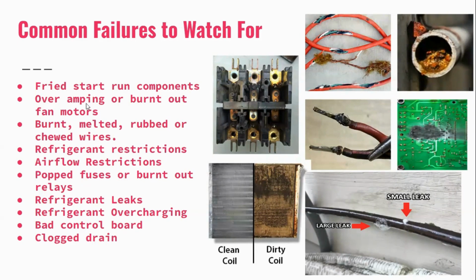And the reason I say always make sure you have an amp clamp on your meter is because we always want to check our fan motors. When I was starting out, I cannot tell you how many times I went on maintenances and didn't know I was supposed to be amping out fans. Two weeks after I did that maintenance, they were calling my boss saying, hey, my fan motor just went when you guys were just here checking all of that. Sure enough, little Jennifer didn't know she was supposed to be amping out fans.